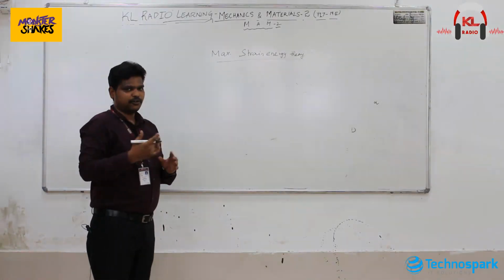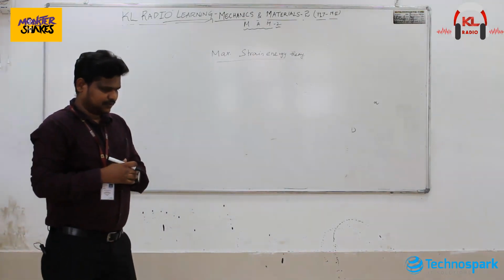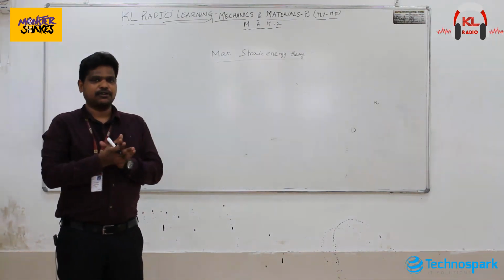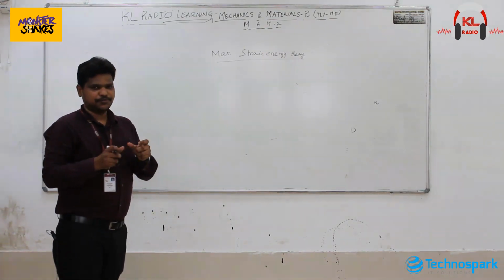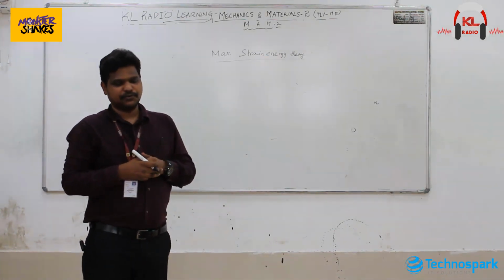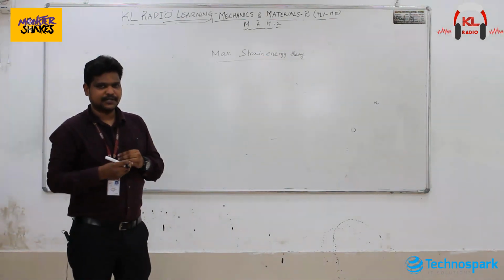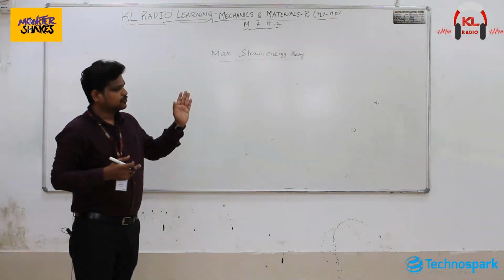So I repeat, for no failure in the member or a machine component or a part, the total strain energy per unit volume in the member due to general loading condition should always be less than the total strain energy per unit volume in the material under uniaxial loading condition. Try to put that in a math form.